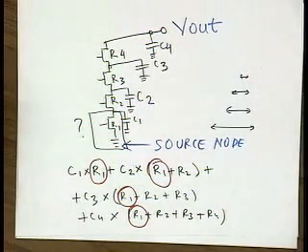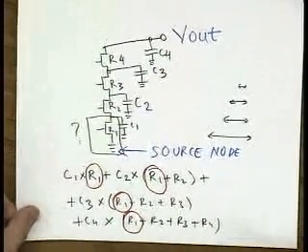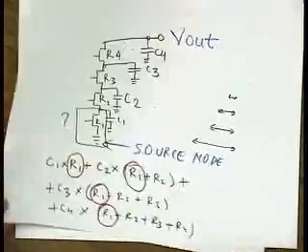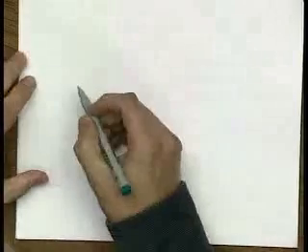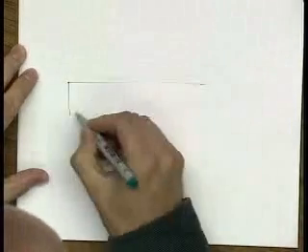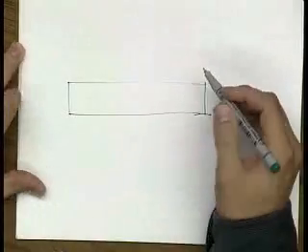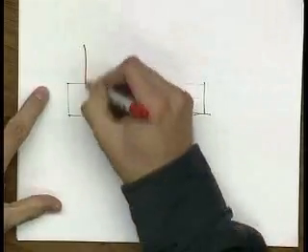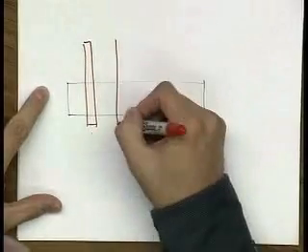But now this comes to the question from the last lecture. Assuming that you are laying out your transistors horizontally, and they have different widths, what are you going to do with your diffusion over here? If all my transistors are the same width, I'm good with that, and these are my poly lines.